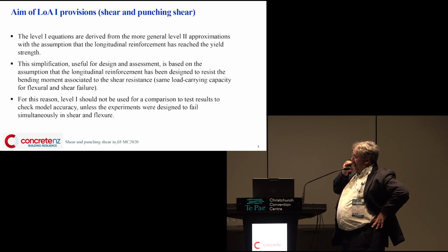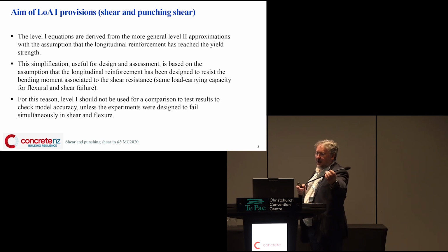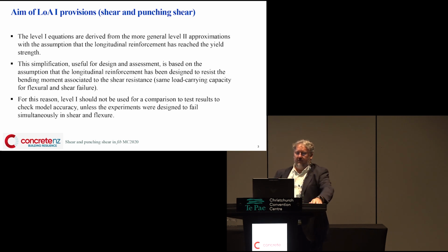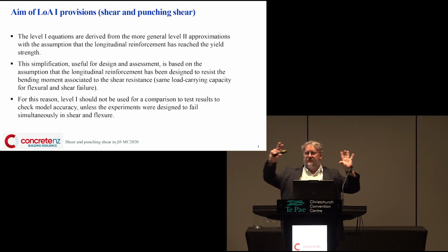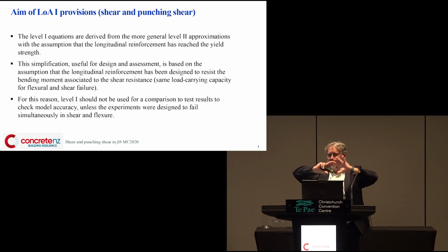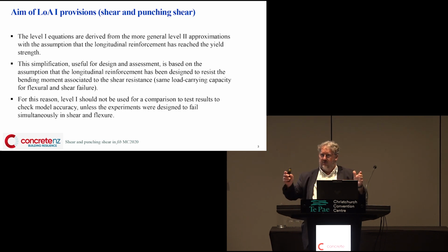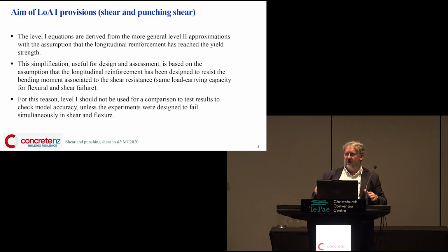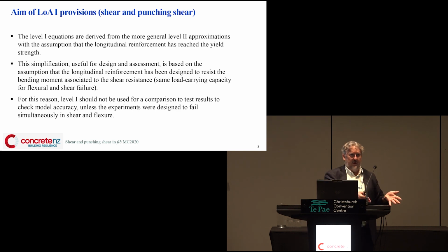All right, so level 1 equations are really derived from the higher level 2, level 2 derived from the higher level 3. Now, ideally, what you would have is one consistent formulation, which is your highest level equations. You would then simplify those down with some restricted parameters, so that's your level 2, and you might have simpler versions of that. So if I'm doing a new design and shear is not going to be critical, I don't need to do the very high level calculations. I've just got to justify it using the lowest level. It's usually a nice simple formula.